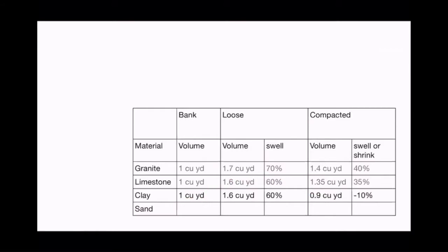Now, I've written it here as negative 10%, but that's a negative 10% swell. Really, what we would call it on the site or in our meetings with our subcontractors, we would call it a 10% shrink factor. And that would let us know how we can balance the site, and we can flatten it out for a driveway or flatten it out for a plaza or something like that.